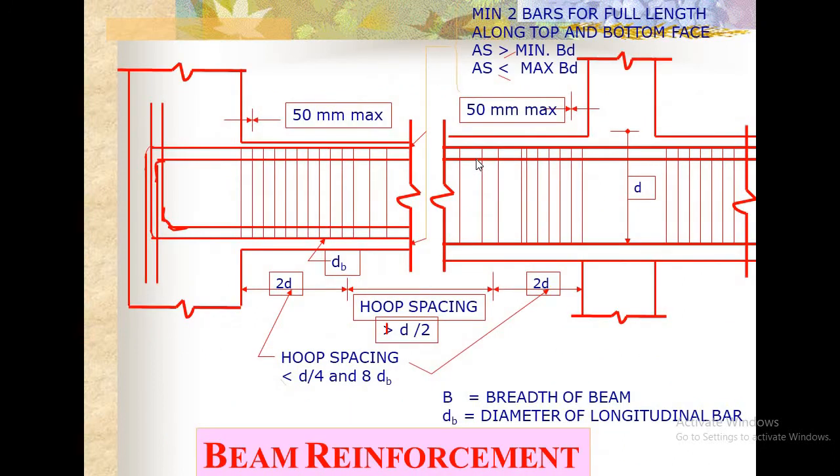You see, it's a typical beam reinforcement in the consideration of ductile detailing. I think you will be familiar with how to provide the reinforcement in a beam. In the bottom there will be a tension reinforcement, at top there will be a stirrup holder. If necessary, you should provide some positive moment reinforcement near to the support.